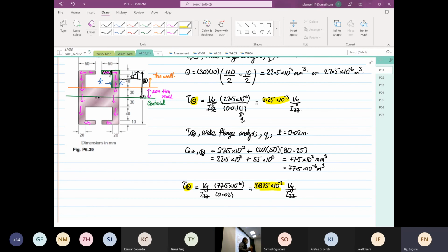You are looking at it from a different perspective. You're not wrong, you're right. When it's a box beam, at the terminal, the Q splits, one towards the left and one towards the right. That's why you divide by 2. You can look at it as, Eugene, I'm going to divide the area by 2. But I'd rather teach it with the terminal, because later on, when I have more complicated shear flow, you have to grasp that concept. You're not wrong, you're correct.